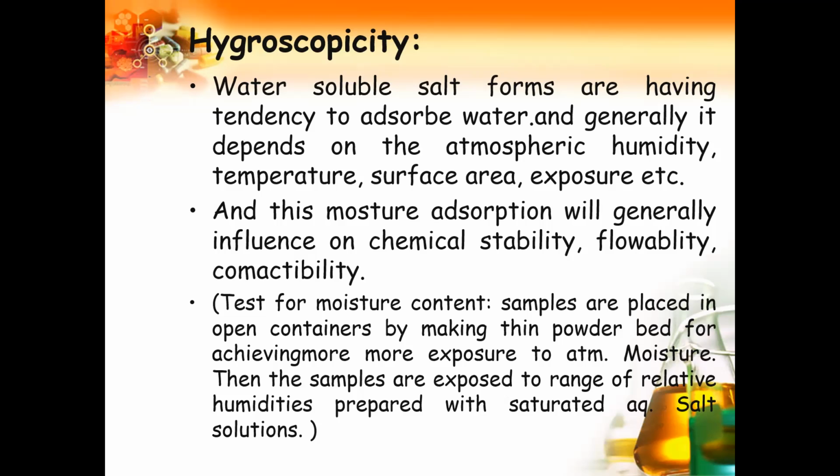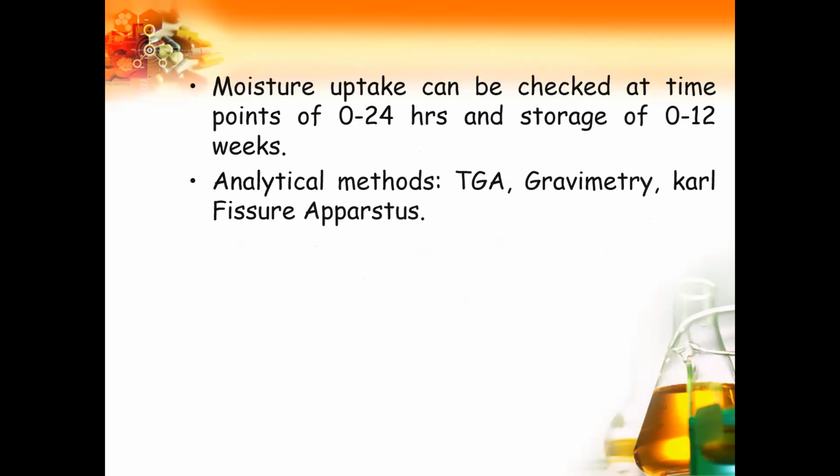Then how can we measure the hygroscopicity? There is one test, that is a test for moisture content. In this, samples are placed in open containers by making a thin powder bed to achieve more exposure to the atmospheric moisture. Then the samples are exposed to a range of relative humidities prepared with saturated aqueous salt solutions. The salt solutions are made up of different humidities.